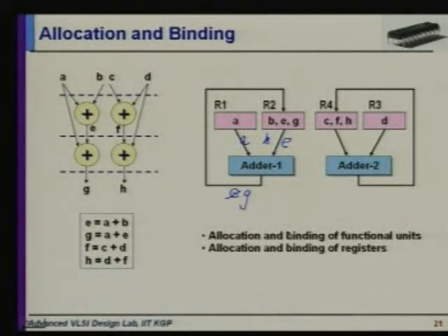And we want to reduce the number of registers. So what do we do? There is a very nice problem. You take each variable and note down the time period for which it is active, the number of cycles for which it is needed. So let's say this is my time. I need A from here to here, and this is not this example, so let me use some other variable names.